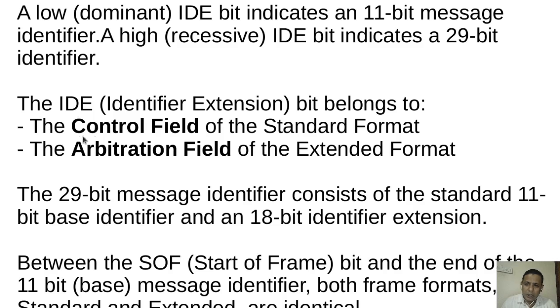So the IDE bit belongs to the control field of the standard frame format, and to the arbitration field of the extended frame format. A 29-bit message identifier consists of the standard 11-bit base identifier and the 18-bit identifier extension that we have seen. Between the SOF, the start of frame bit, and the end of the 11-bit base message identifier, both frame formats,